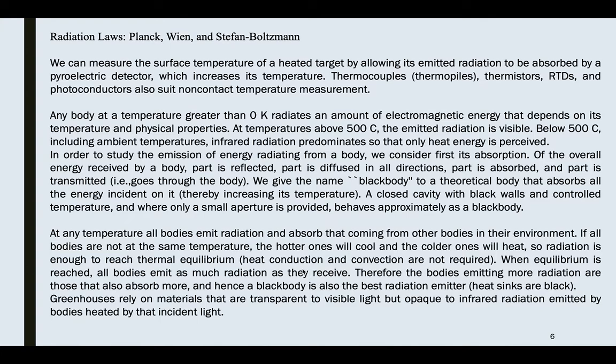A closed cavity with black walls and controlled temperature, where only a small aperture is provided, behaves approximately as a black body. At any temperature, our bodies emit radiation and absorb that coming from other bodies in their environment. If the bodies are not at the same temperature, the hotter ones will cool and the colder ones will heat. So radiation is enough to reach thermal equilibrium. Heat conduction and convection are not required.